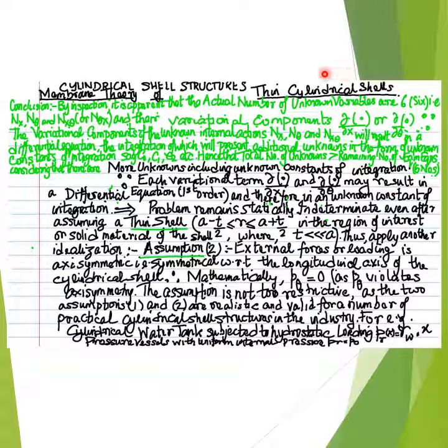while the third moment equilibrium equation sigma mr equal to 0, that is the rotational equilibrium equation for the differential thin cylindrical shell element, required that the two in-plane internal membrane shear forces nx theta and n theta x should be equal and opposite to each other and therefore nullify each other.